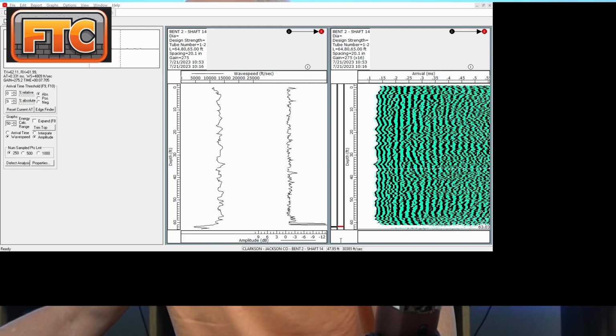And of course, you need to ferret out an issue with the drilled shaft concrete itself versus things that are merely a data issue from, say, access tube debonding. So for this example, we obviously have questionable to poor quality concrete in about the bottom 2 feet of the shaft. And I say questionable to poor quality concrete, we see velocity reductions of 10 to over 50%.